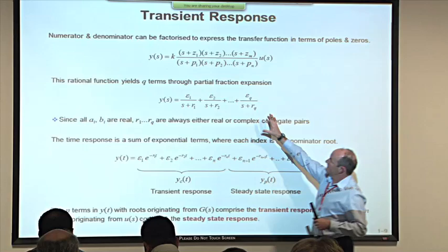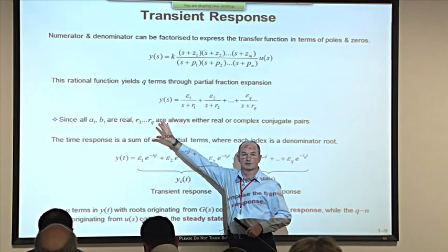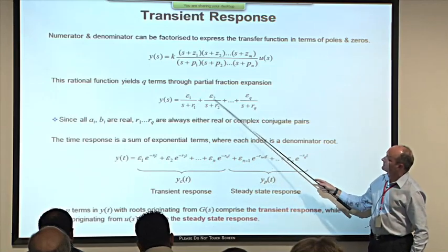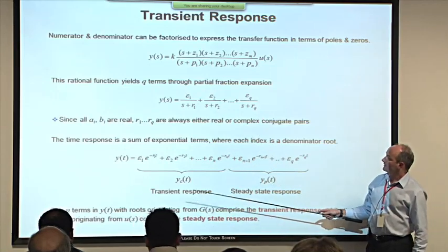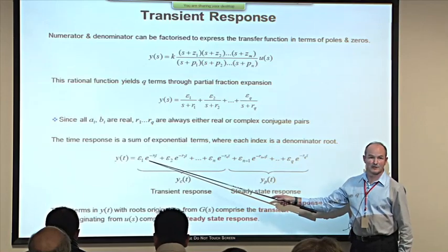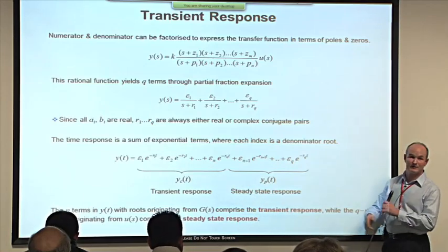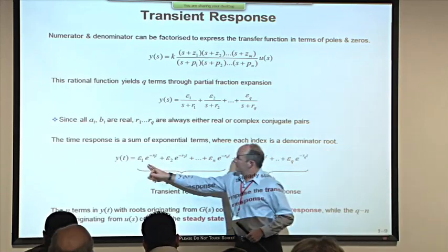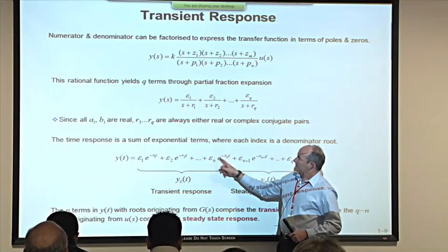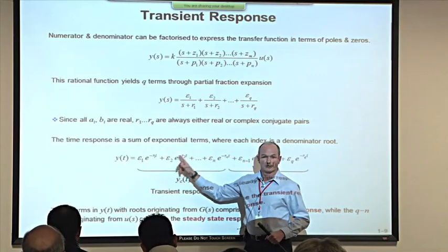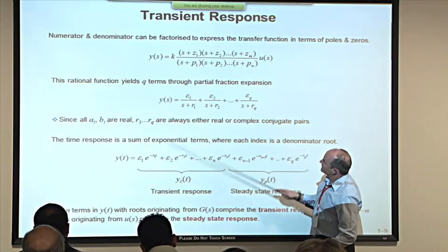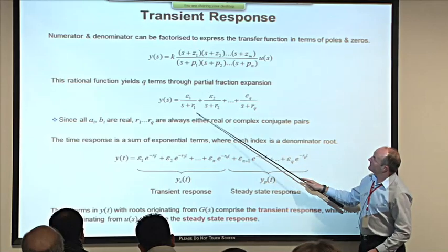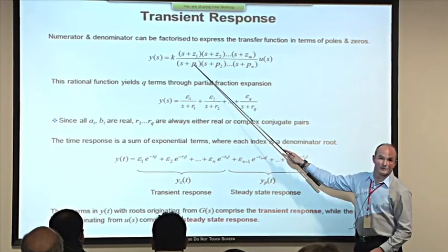And when we take an inverse Laplace transform of this partial fraction expansion, we find a series of exponential terms, because each of these first-order terms has an exponential as its inverse Laplace transform. So you end up with a series of exponentials here if U(s) is as I've just described. Now, look at these exponentials and recognize that the exponents in each of the first n terms come directly from the denominators, and each of these comes directly from the poles of the transfer function.